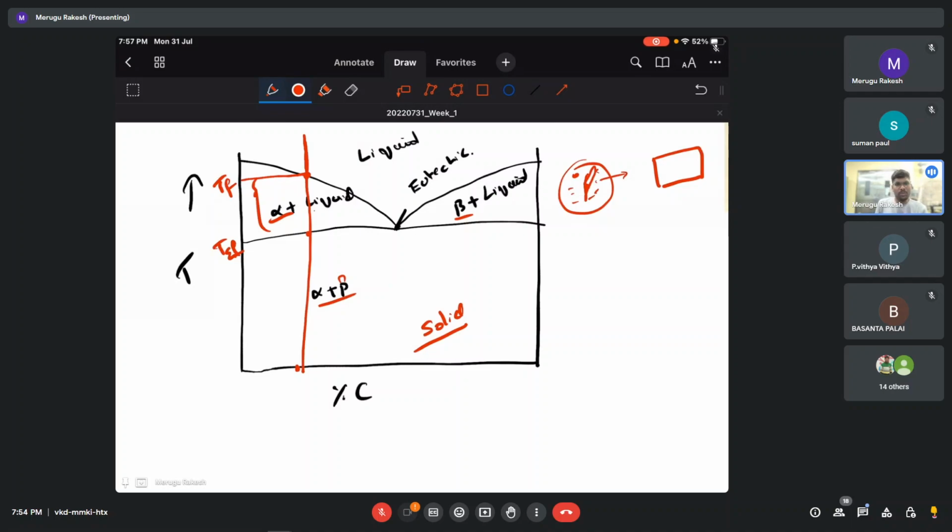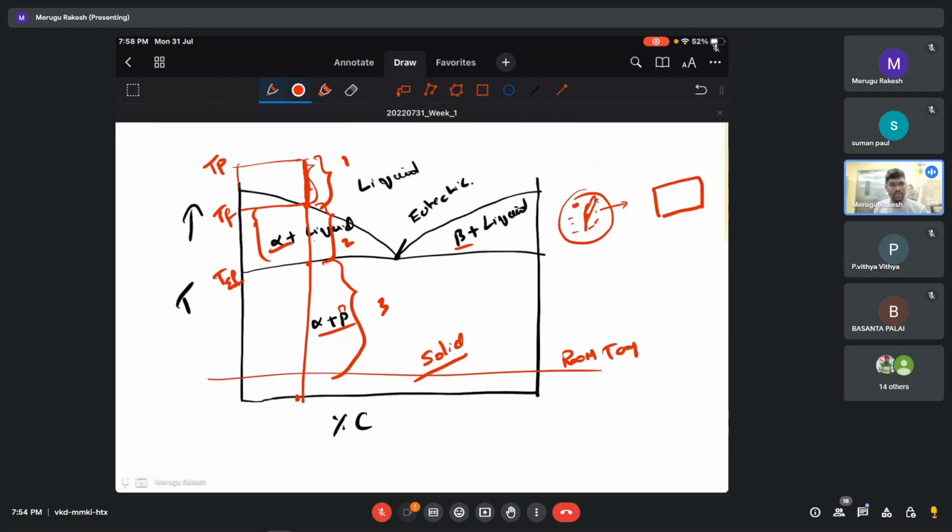We are going to learn more about what happens in this region as well. This is a very brief picture of what solidification is. We actually pour at some higher temperature, the pouring temperature. So we will get some shrinkage there, then shrinkage here because of the phase change, then shrinkage from here to here, say this is room temperature. So we have three types of shrinkages. I hope this clarifies what happens in solidification.